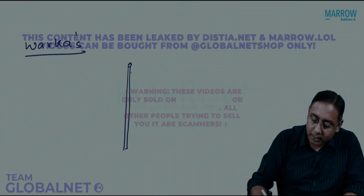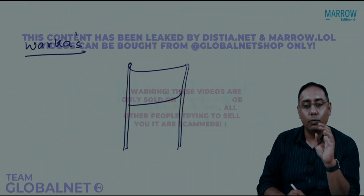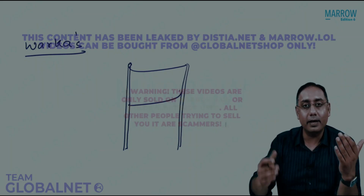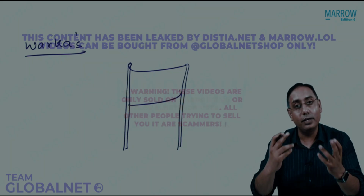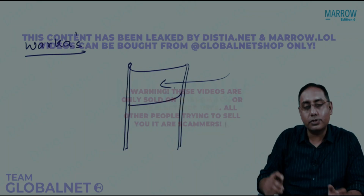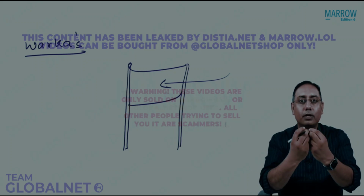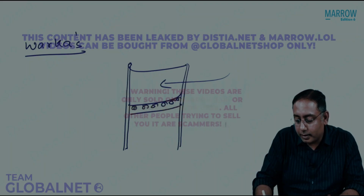What happens in a Varka is they keep a pipe and put a big cloth over it. That cloth has a specific pore size. In deserts, in areas where there are fewer trees, there is a lot of wind, and that wind could carry some moisture. So what they do in a Varka is take the water out of the air. Such a beautiful thing. The air in the night strikes this cloth, and the cloth takes out some water. It becomes damp, and the water gets collected at the bottom.